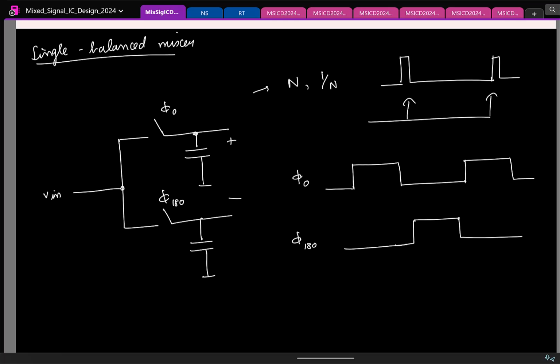Because ideally you want impulse sampling, but in practice you can't do that, so that's why you do this square wave thingy. If you look at the Fourier series component, the fundamental strength in a square wave will be smaller than the fundamental in the impulse. And if you have n of them, this is better.